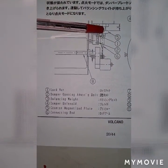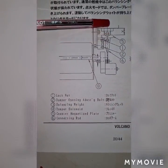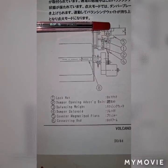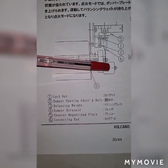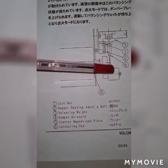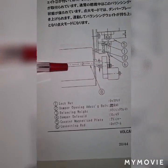This is the air damper, and this is my transformer type actuator. Once the transformer here is energized, it will pull these counterweights. Once this pulls, it will close the air damper.